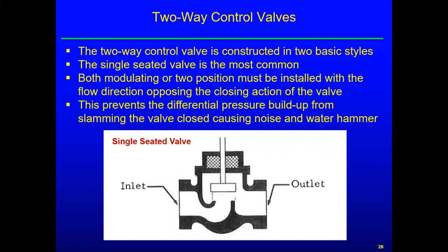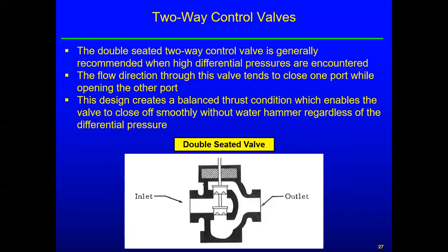There we go. So that differential pressure, that valve closing against the flow coming in, prevents slamming the valve closed, causing noise and water hammer in the system.